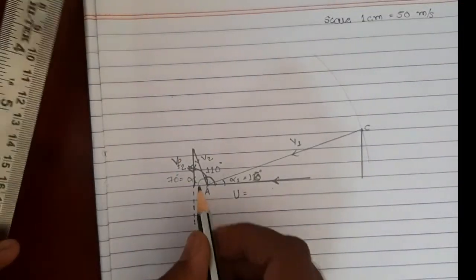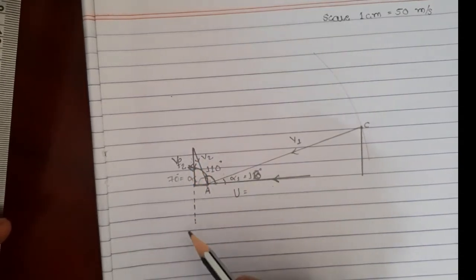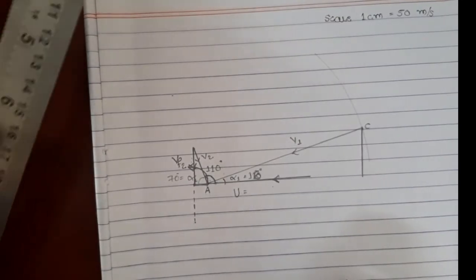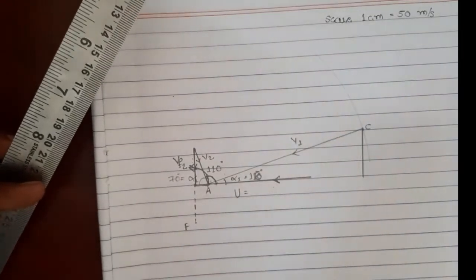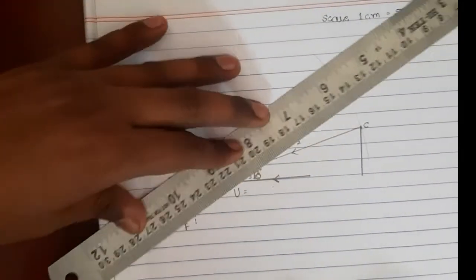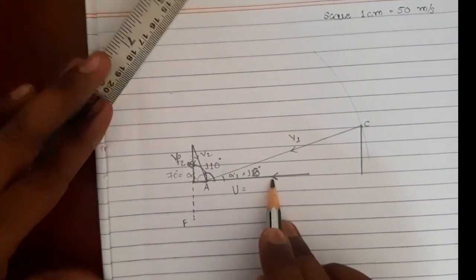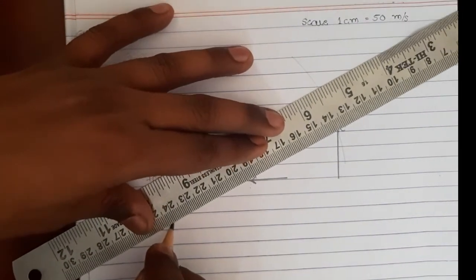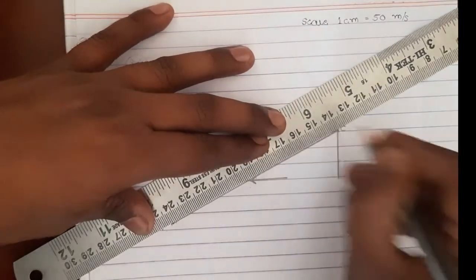Right? Then what I will do? I will cut it. Here what I have done? I have taken the length of VF2 and I have mirrored it downwards. The same length I have drawn in the below section. Now I will join point C and this point F. So the point where the line joining C and F cuts this line gives U, thereby I can measure U. Here to here, if I join, it cuts somewhere along here.